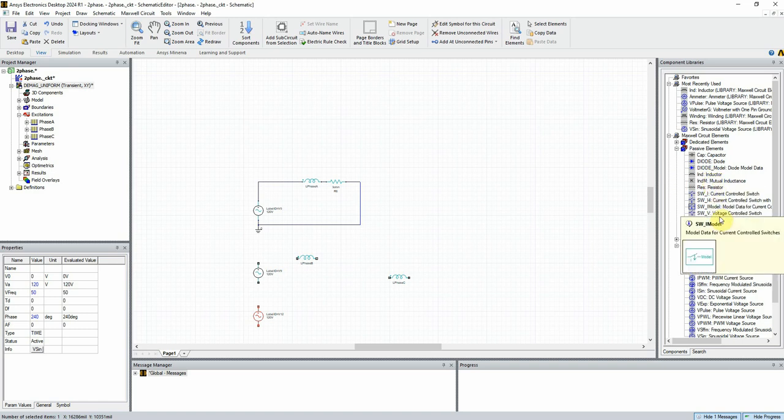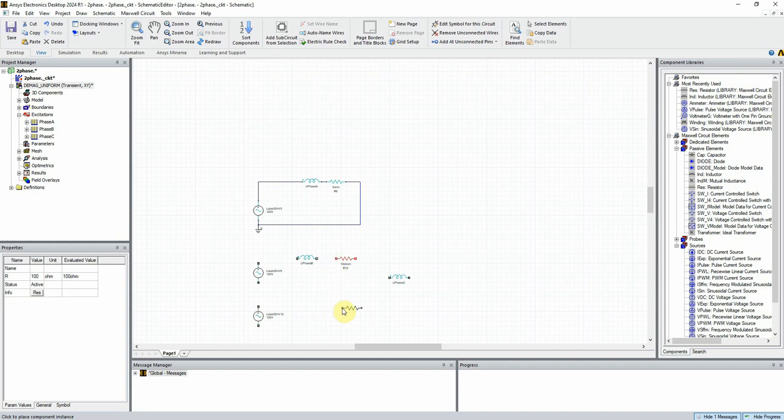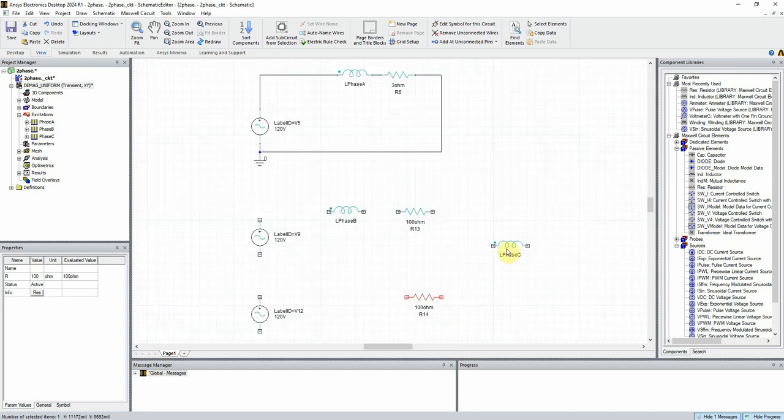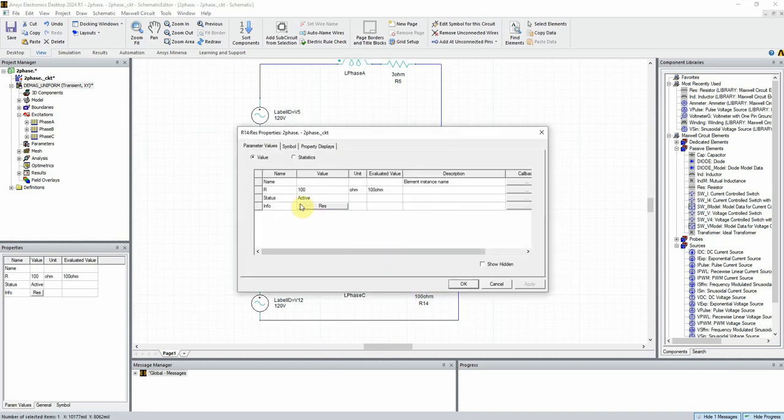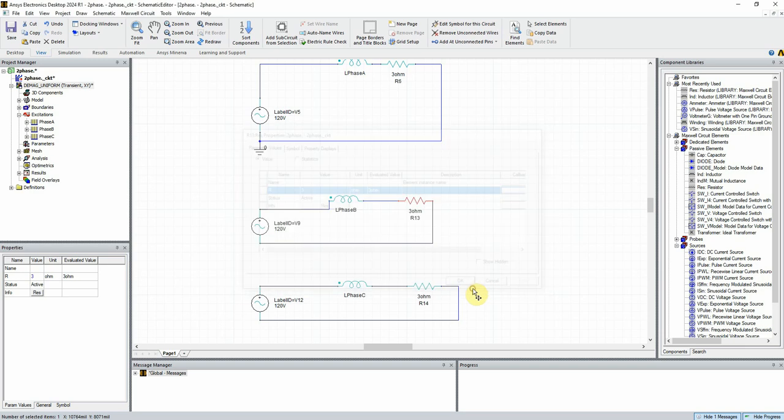We need resistances here too. Resistor, 1 for phase B and 1 for phase C. Let's complete the circuits by connecting them with the wire. Don't forget to put the ground to the independent circuits too. Make the values right again, 3 ohm for the resistance of the windings, and we set the voltage source before. So the circuits are completed.